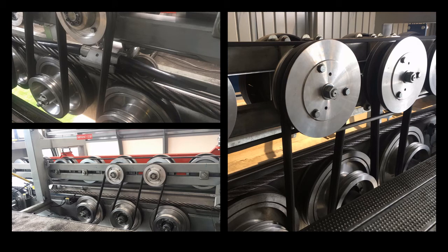The tires in the tire banks are powered via a direct mechanical connection to the haul rope called a power takeoff, or PTO, system. The haul rope will spin large PTO sheaves that are connected to several tires in the tire bank via a grooved rubber belt called the PTO belt. All of the other tires in the tire bank are then connected to these two tires via rubber belts.